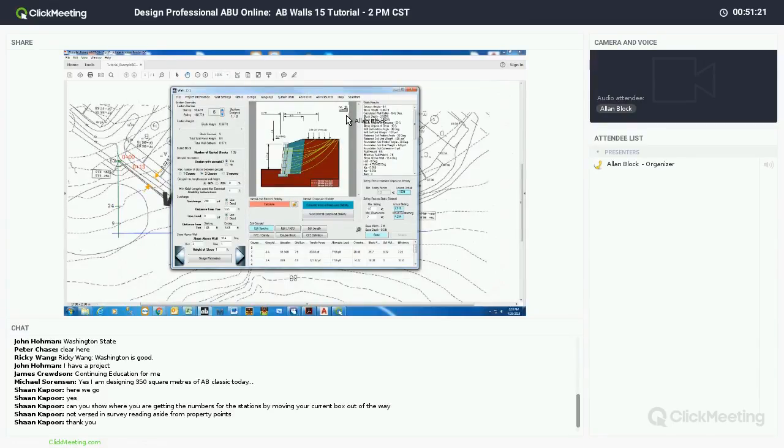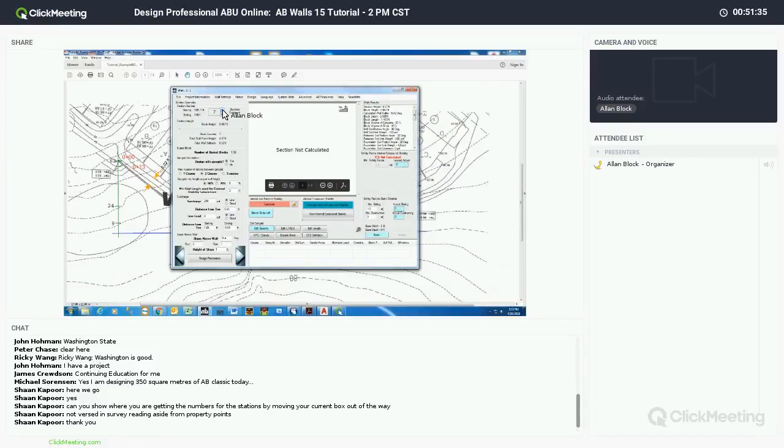All right, so we've run slope, surcharge, we've run our internal calculations, all of our safety factors are above the minimum, so we have a good design. I'm going to move on to the next section. To do that, I'm going to use the little blue arrows next to our section 6, going in either direction because I am going to have to cover them all at some point.